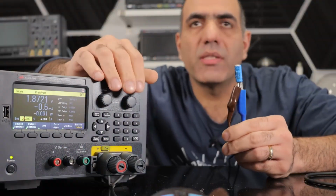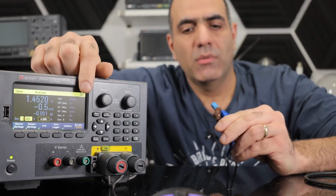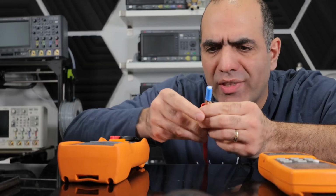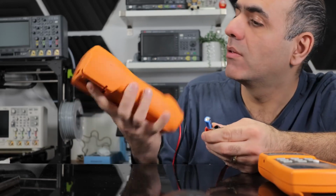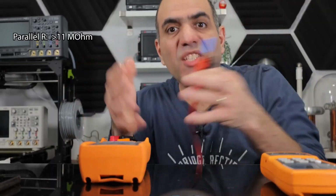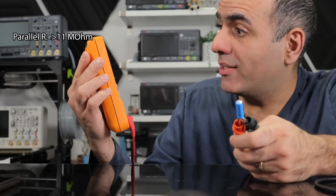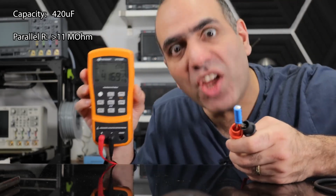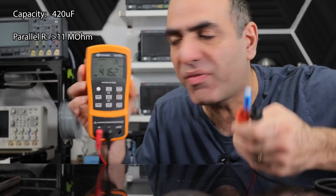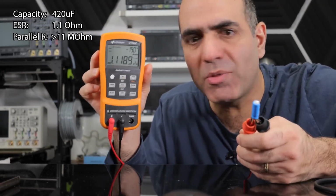I guess this is a much smaller explosion compared to what could be. I'm pretty sure this is a half-blown capacitor now. Measuring the parallel resistance, it's well over 11 megaohm now. Well, the good thing is that the plates are not shorted, so it should still be able to capacitate. The capacitance now is only around 420 microfarad, dropped way down from the original 2200 microfarad. And the ESR now is 1.1 ohms, over 10 times what it was before.